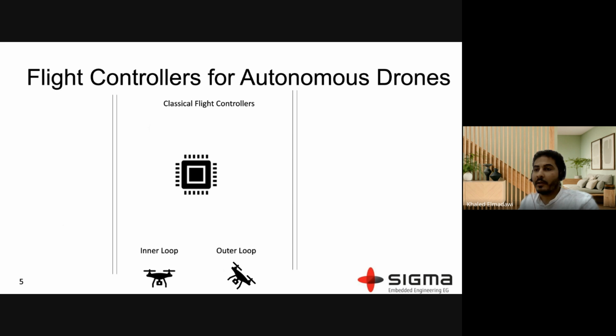It helps the drone to achieve what is required from it through observing the vehicle states, making a state estimation on the observed and the non-observed states, processing the control loops and outputting stabilized control signals to the motors, and finally communicating with the pilot or the ground station in order to achieve the required mission in a correct manner.